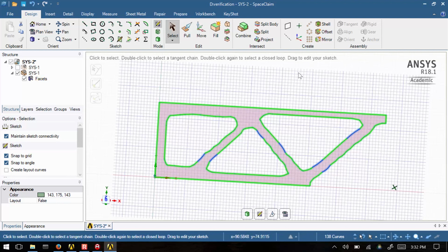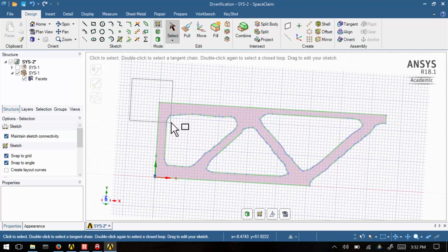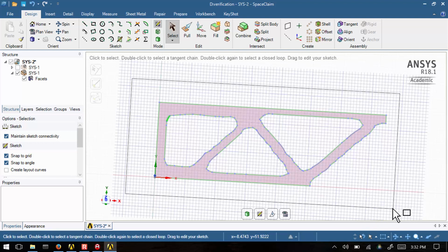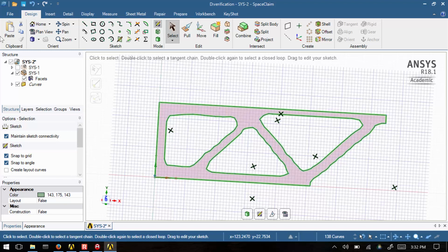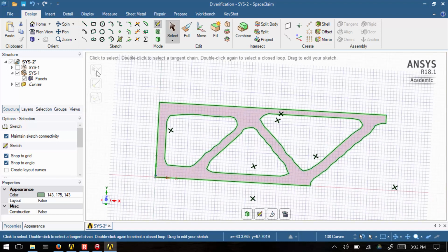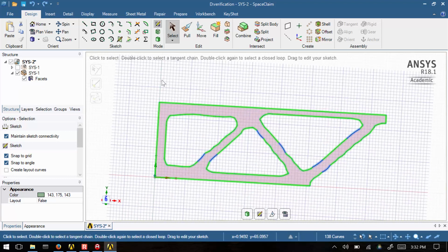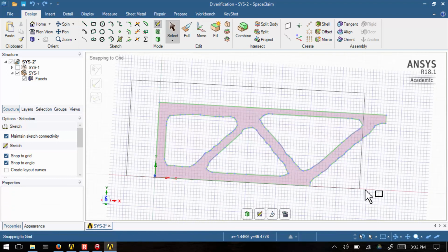And then what I'm going to do is, on the design tab there's a copy button and a paste button. So first thing I do is select, after I get my plane, select all the geometry, just with the box select. Then I'm going to click copy or Control C, and I'm going to do paste or Control V. So copy then paste, and what that does is it just puts that geometry on that sketch plane. Okay. So again, you can use Control Z to undo things. So again, I just selected all the facets from my sketch plane,